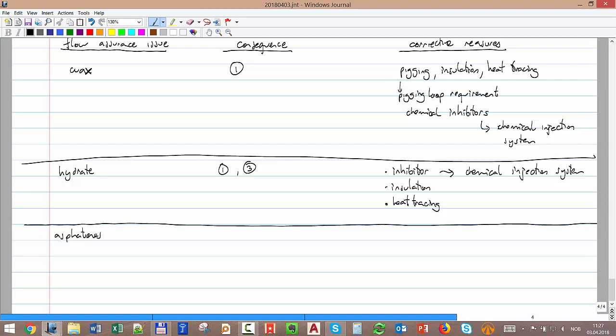Okay, asphaltenes can also lead to blockage, and can lead also to loss in functionality. And what kind of measures do we have for asphaltenes? You were asleep? Yeah, chemicals. Okay, they say that actually we have to know that they are there, but basically I can use some chemical inhibitor, but at the end I need some kind of mechanical removal.